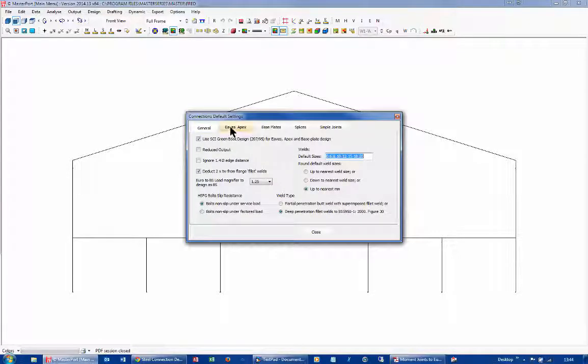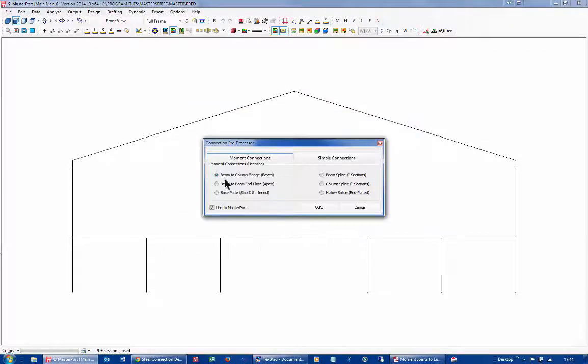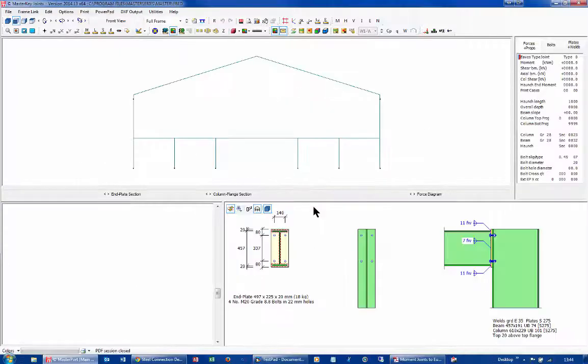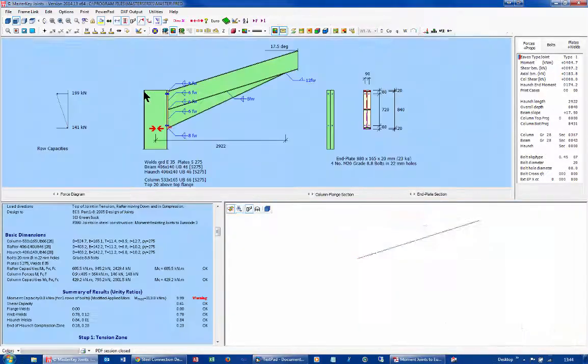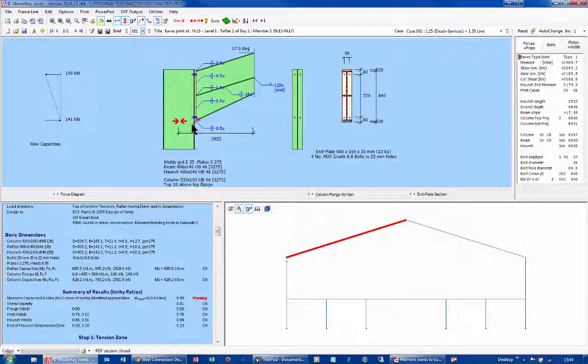And I am going to first of all do my typical eaves. Yeah, let's go for one. Now, it's asked me where, and I just pick on the rafter somewhere down near the bottom, and it pulls out, and obviously I've got quite a long haunch. I don't need to draw that whole haunch, so just turn that off. That looks a wee bit more respectable. Quite narrow 140 beams coming on to 165, so it's quite tight.